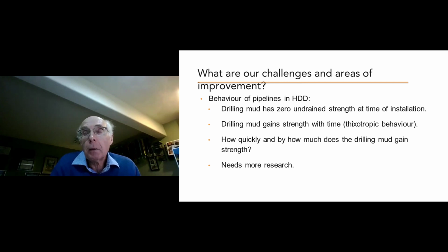But the owner of the pipeline then went out and got an independent assessment, which is certainly their prerogative and often a good idea. And the reviewers came back and said, well, where did you get the strength of the drilling mud from? After discussions, we conceded that there was very little information on this and that it was an engineering judgment estimate. As a result, the reviewers said to the owner, well, if the stress analysis people cannot provide a documented strength for that value, then you should use zero.